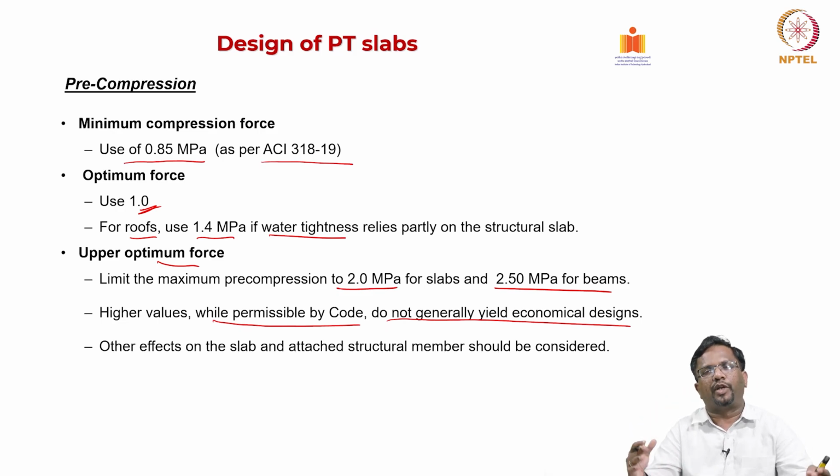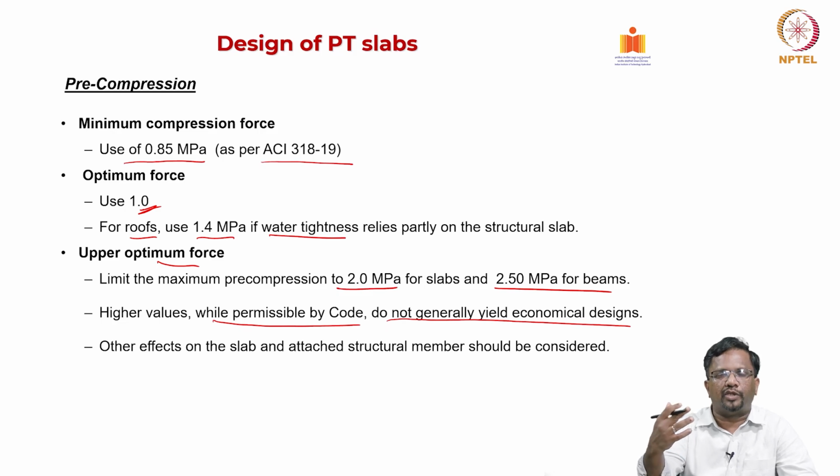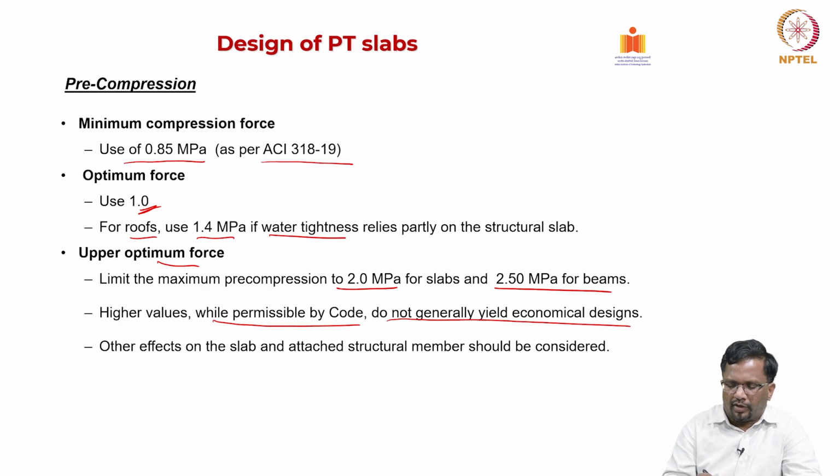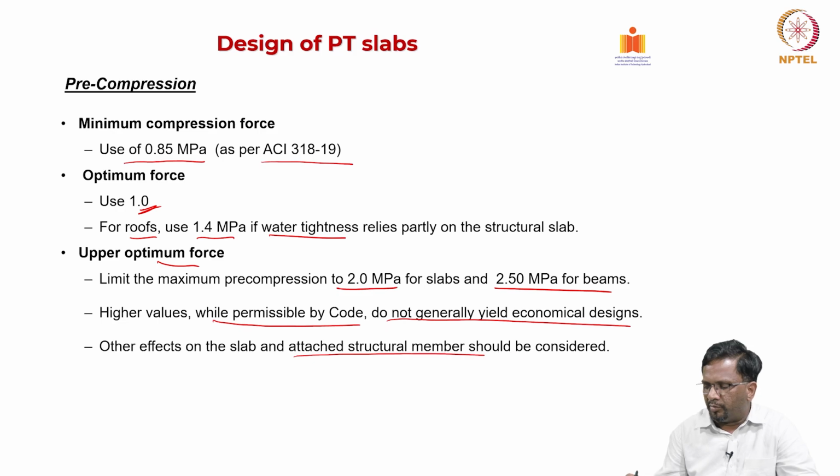Because I have created an opposite effect, we should also receive the loads in time, so that it is going to relieve some of the excessive stress that you have locked in due to pre-stress, right. So, that is also something you have to keep in mind. Other effects, such as on the slab and attached structural members, should also be considered.